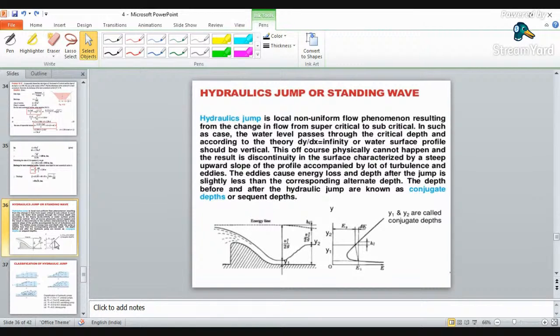But when we are talking about rapidly varied flow, there will be a sudden change in the velocity, in the depth, as well as in the other characteristics of the channel along the length of this section. So, because of the rapid change in the characteristics of this flowing water, there will be formation of a jump from one end to another, and that jump will lead to a loss or dissipation of energy. Okay, so in simple language, what is a hydraulic jump?